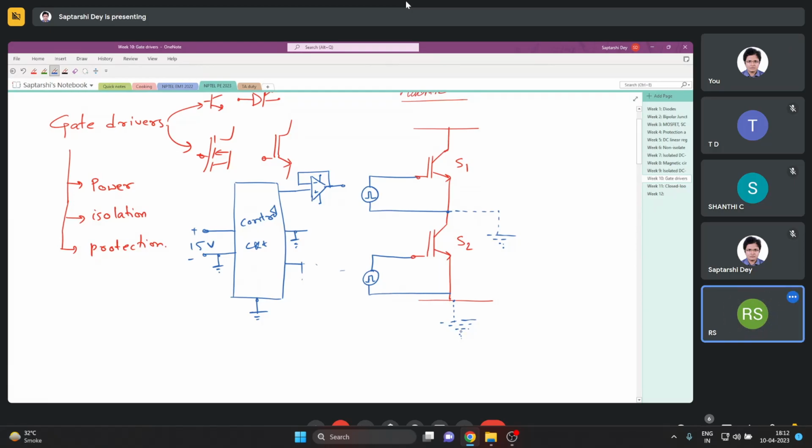So all the gate terminals will be getting some PWM from the output of the controller. And the controller is the same. We are not having a different controller for different switches, right? We have one controller, and the controller is supplying all the switches. The controller output goes to a buffer. Buffer means that it has the capability of giving current to turn on the switches, and that is connected to the switch bases.